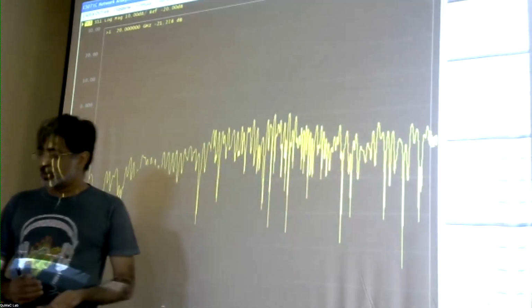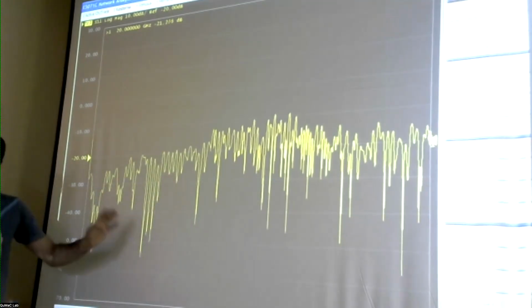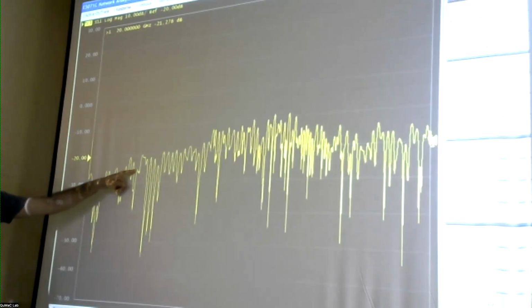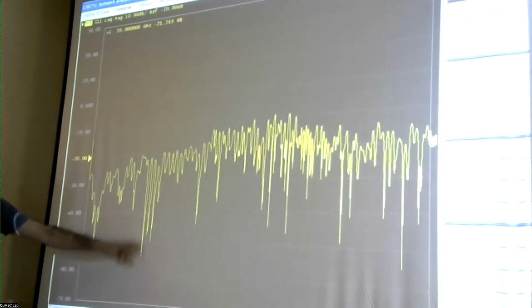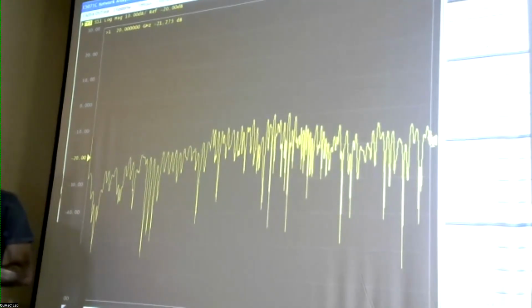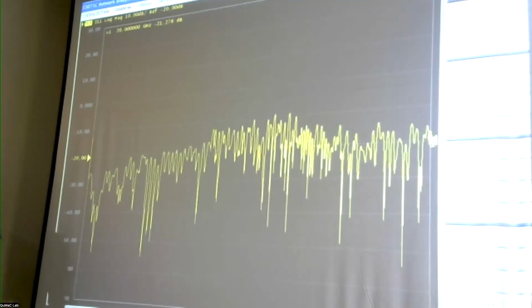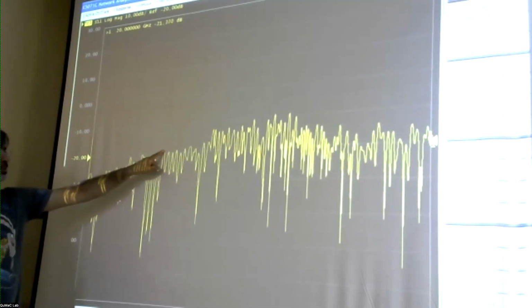So this is again a very typical trend that at higher frequencies, the reflections will typically get worse. These weird dips you are seeing, again, because of the log scale, this looks very exaggerated. Suddenly it looks like it's a very good cable at this point of time. In practice, there is very little difference between this point and this point. And these happen because of interference. Both sides have reflections. And at certain frequencies, some of those reflections can actually cancel each other out and give you a nice destructive interference to give you these dips. And at other points, they actually make it worse. And those correspond to these peaks.